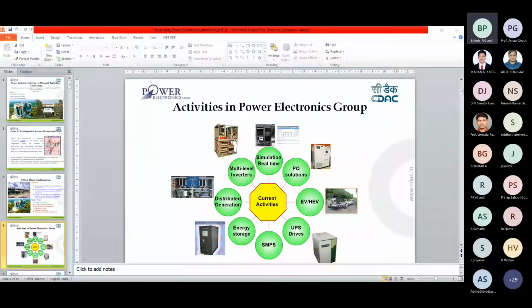All our indigenous systems we installed there. This is the scheme. The major source is 25 kilowatt solar PV, and a 15 kVA diesel generator is also there, and a 360 volt 300 Ah battery bank also installed in the control room. These are the major energy resources we used in the installation.